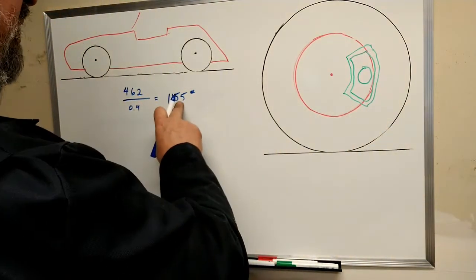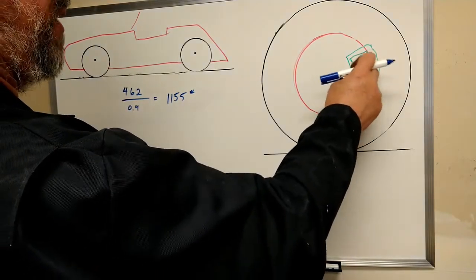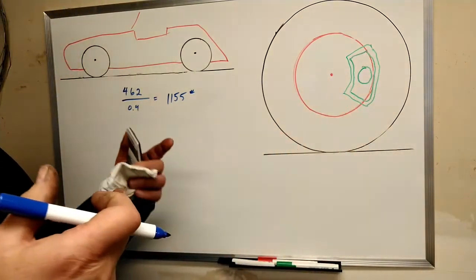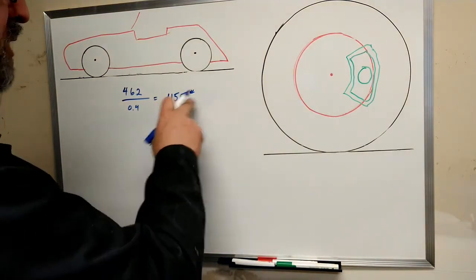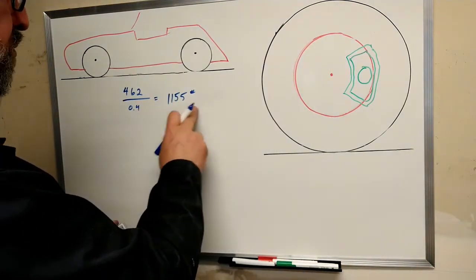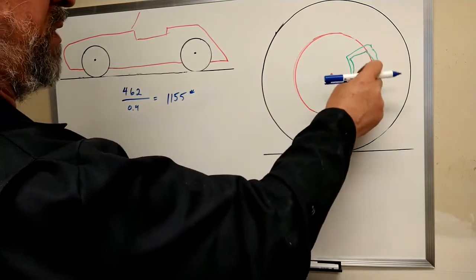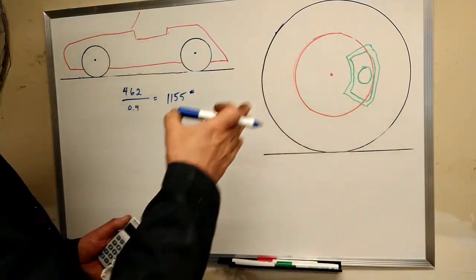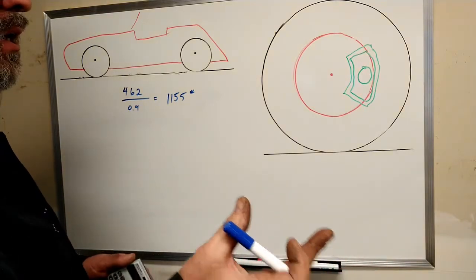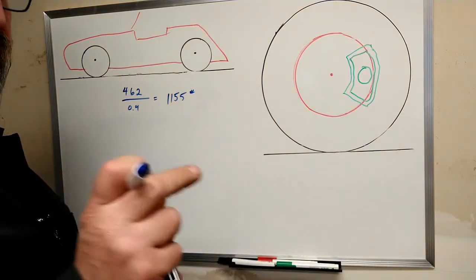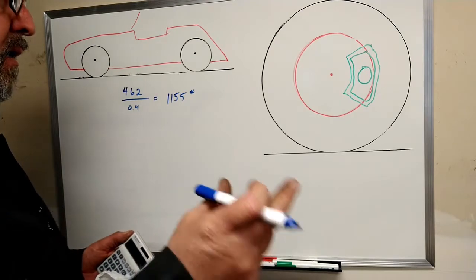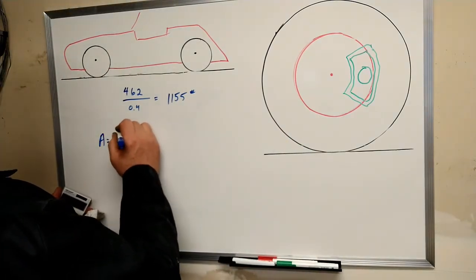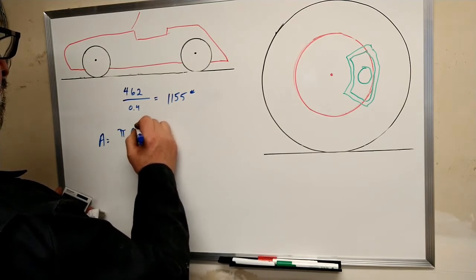Now that is divided up over the piston. The piston is pushing into the pads, so that's what generates that force, and that is then over the area of the piston. The pistons in the front of a Miata, and the ones that I'm using, are 2-inch diameter pistons. So area equals pi r squared.